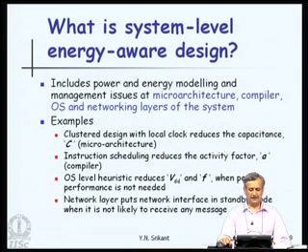Instruction scheduling reduces the activity factor A, and this is a compiler level optimization. If a function unit is not used for a few cycles, based on the history of usage, the architecture would have switched off the function unit, and when an instruction executes again on this particular unit, it is brought to life. If this happens at random, there may be a wastage of power, because switching on and switching off of the function unit requires much more power than executing something or staying idle.